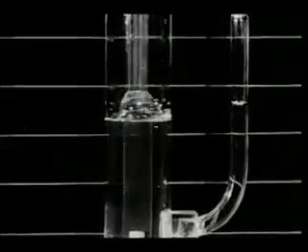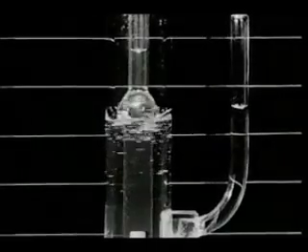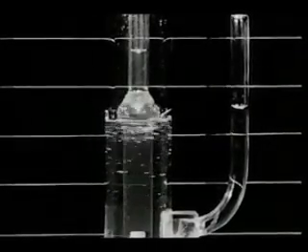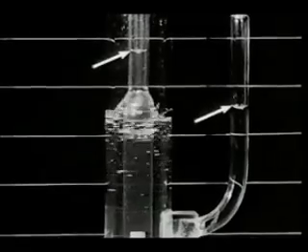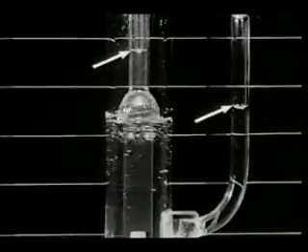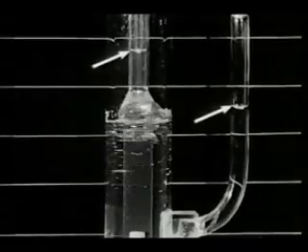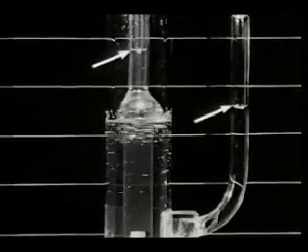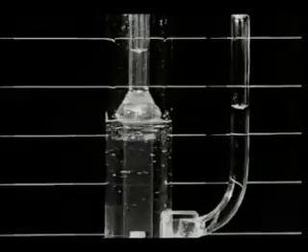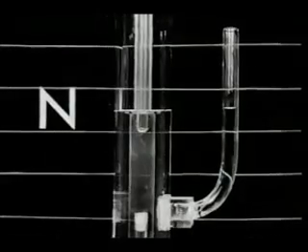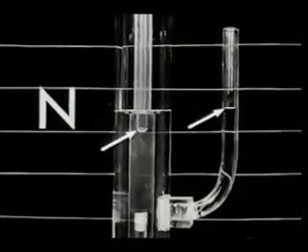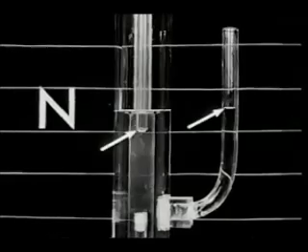Because the fluid is so viscous, it took about an hour for the level of the fluid inside the tubes to indicate the steady-state stress difference. Note that the stress exerted by the fluid normal to the cylinder walls is greater on the inner cylinder than on the outer. This is in contrast to the behavior of a Newtonian fluid, where the centrifugal field alone governs the pressure distribution.